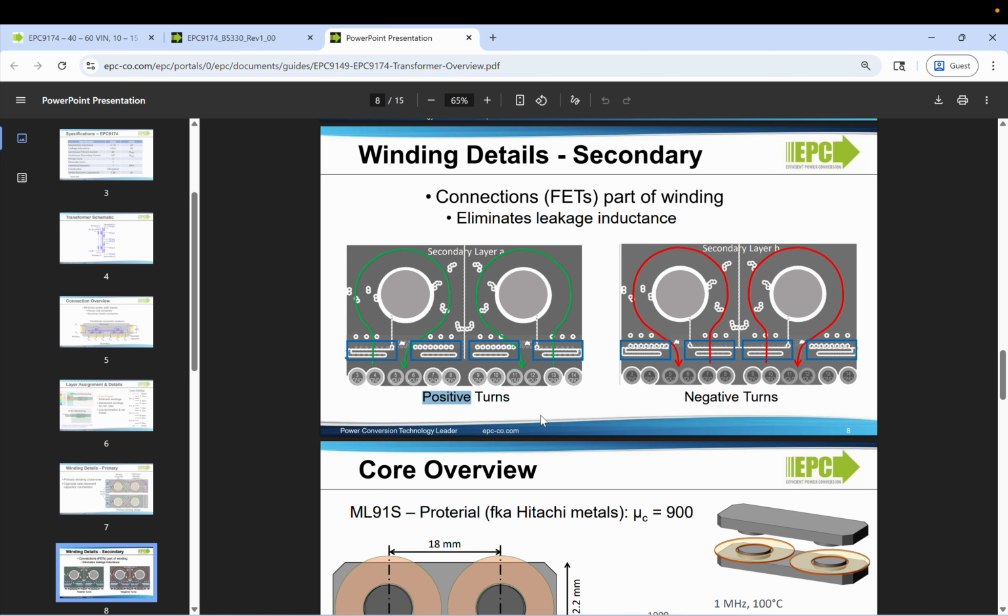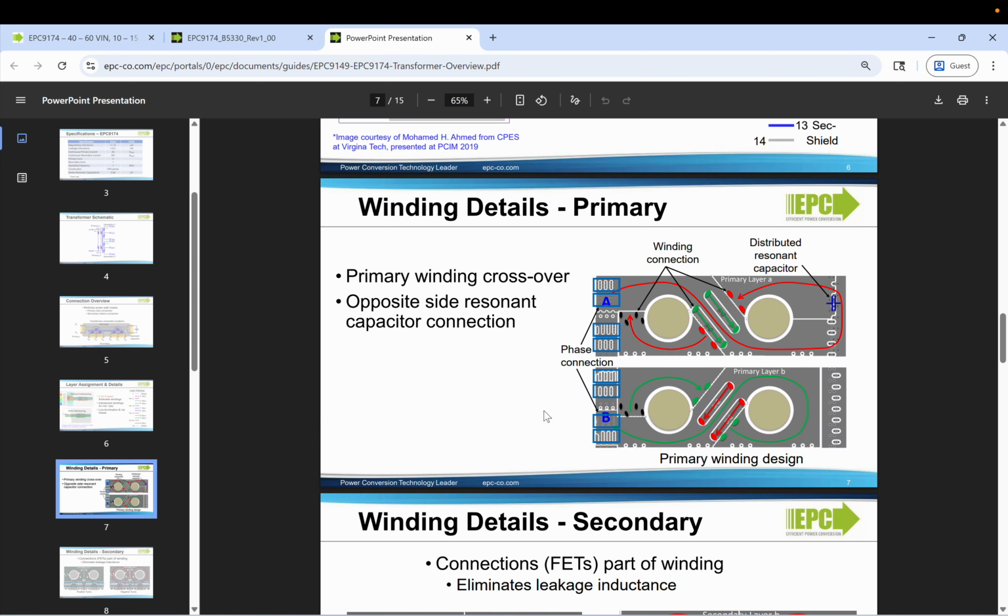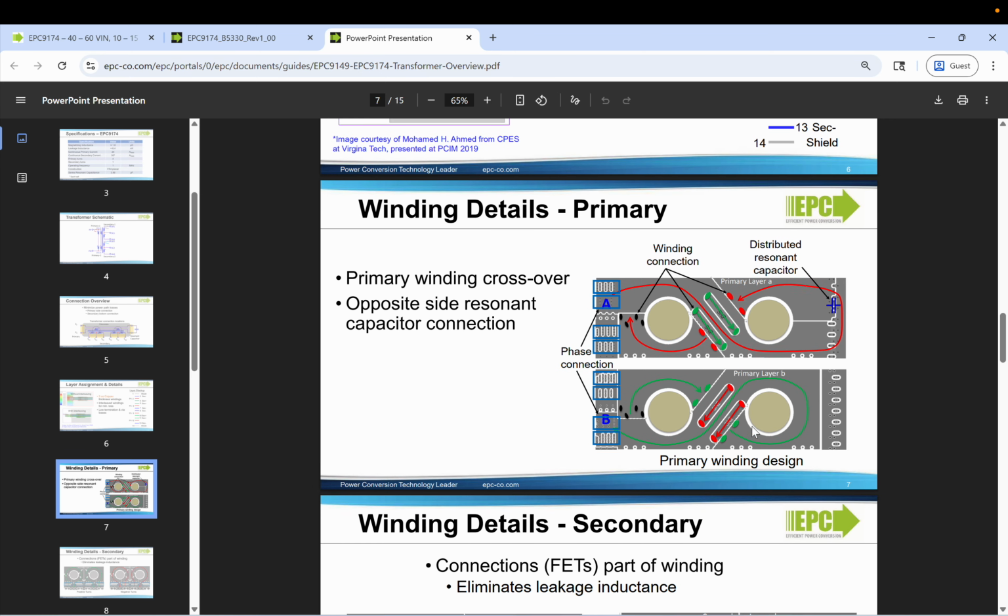And the other point is, in the previous videos I was combining it as a single layer, which is wrong. I'll show you that it's better to take it as a split winding, just one winding here and one winding here, third winding and fourth winding. So there are 4 turns on the primary. This is one turn, this is the second turn, this is the third turn, this is the fourth turn. These are the 4 primary.